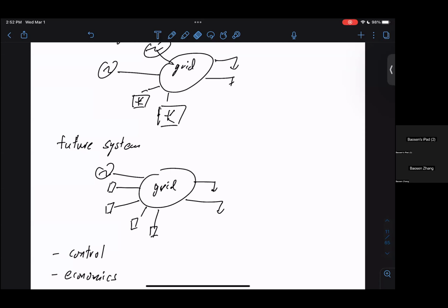That is some order from FERC saying anything connected into the bulk grid has to do frequency regulation. So it doesn't single out a resource, but just says I don't care what it does, I don't care what the type of resource is, you have to do it. I think it came out in 2018. I'm not sure when everybody has to implement that, but it is a rule now. You have to do frequency.